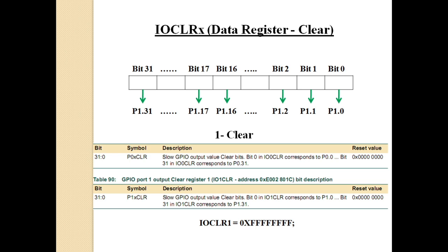What will be the time taken for each cycle? How will you calculate that? You have configured it previously. You are configuring a peripheral known as GPIO. I told you all the peripherals are connected to the VPB bus, and the VPB clock I have configured as 15 megahertz.